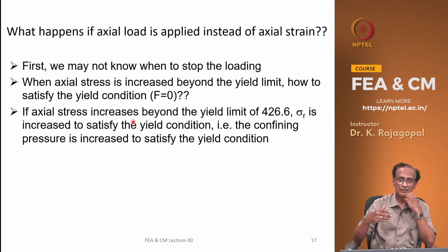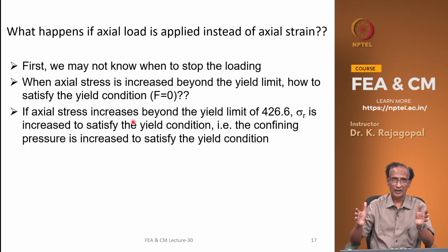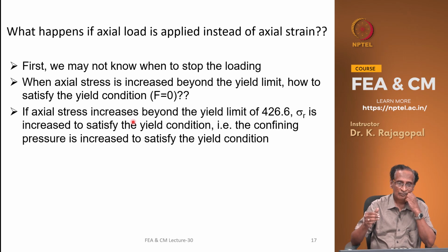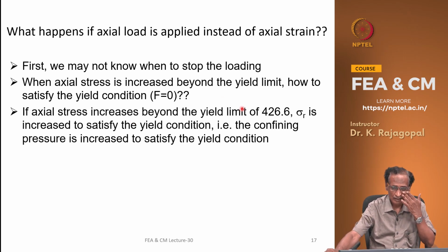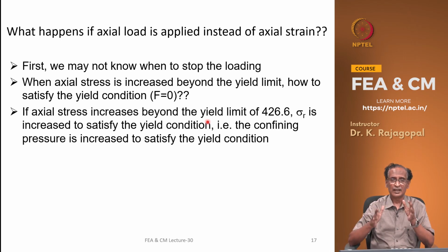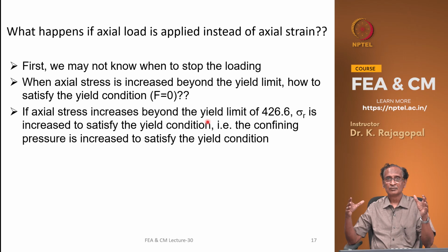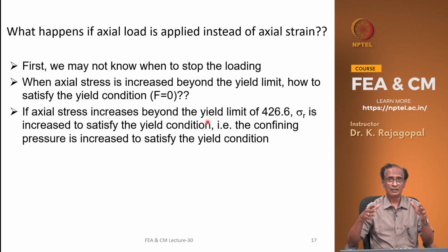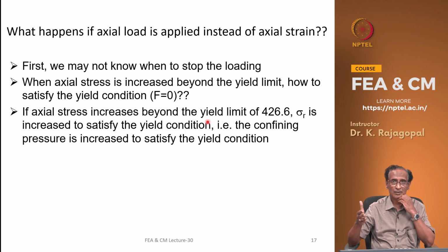So the program or the stress correction method will increase the confining pressure slightly, so that you can satisfy your yield condition. So when you apply the loading up to the elastic limit, your confining pressure will remain constant, but beyond the elastic limit, when you reach the limit state, we will have a problem.